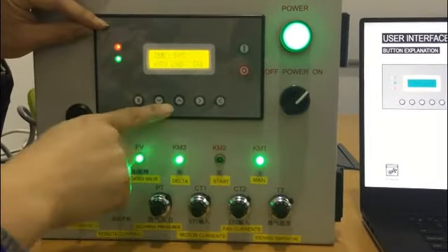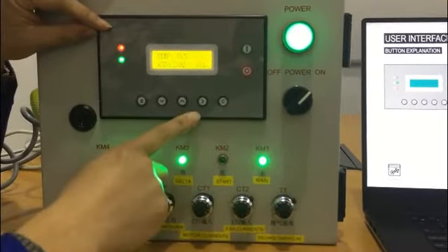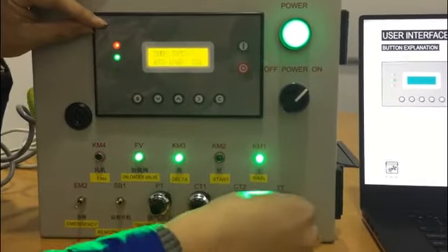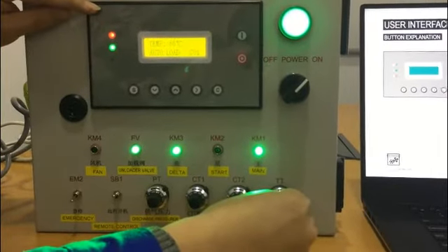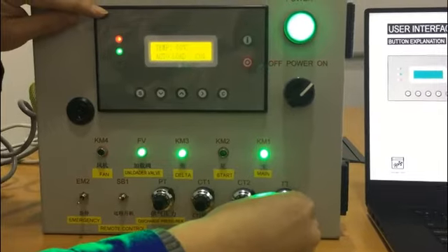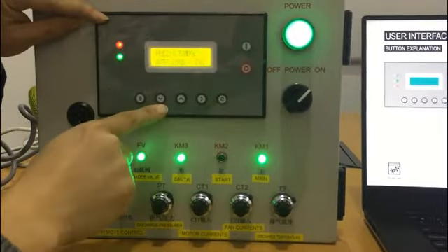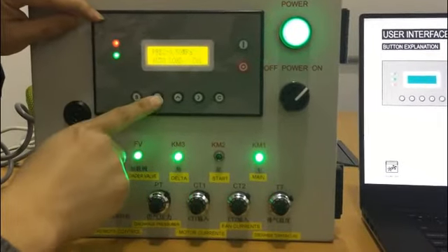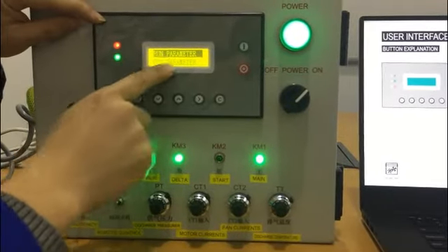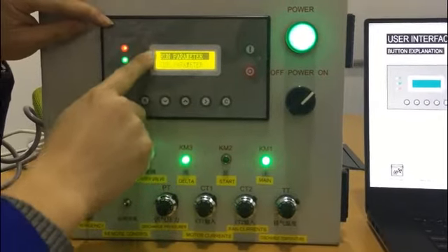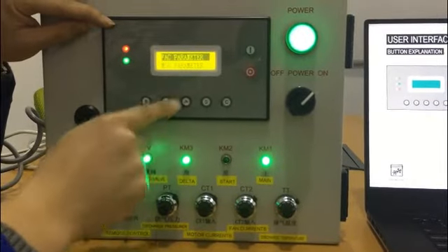And from the main interface, you can see 2 parameters: the pressure parameter and discharge temperature. So you can press this enter button and exchange the parameter interface. Of course, we can turn off this switch and change the temperature, increase it, and switch the interface. And if you press the move down button, you can enter into the manual selection interface. You can see the run parameter, user parameter, factory parameter, and mode parameter.